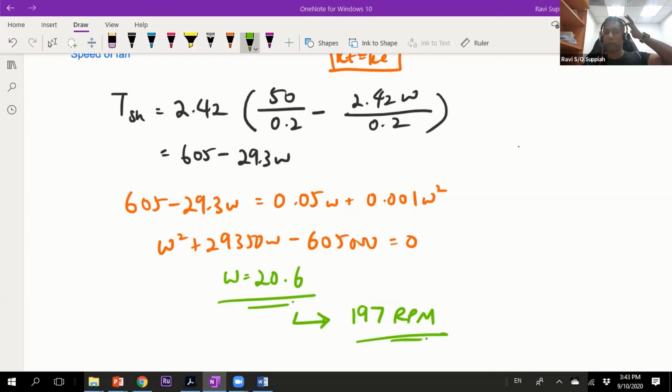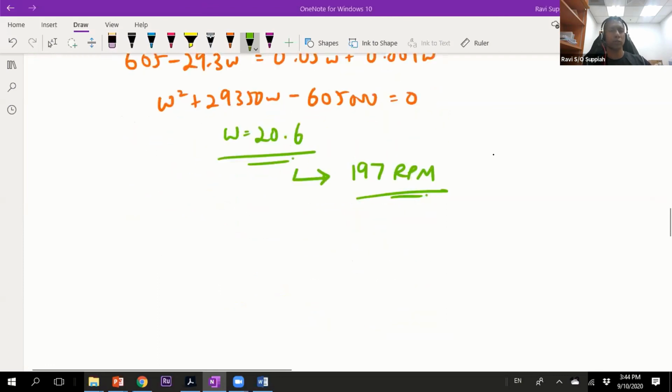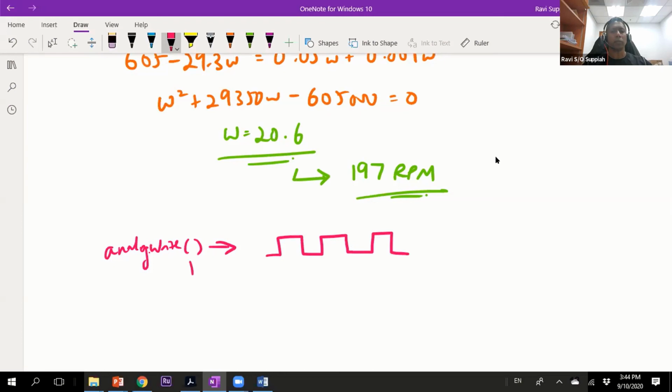So I hope you all have tried the code that I emailed to you for the bidirectional control. In it, there were two options, correct? The short one is basically using the analogWrite function. If you have done the self-learning studio, you would understand that it is basically giving you a PWM. The analogWrite function in your Arduino sketch generates a PWM signal based on the parameter that you pass in.